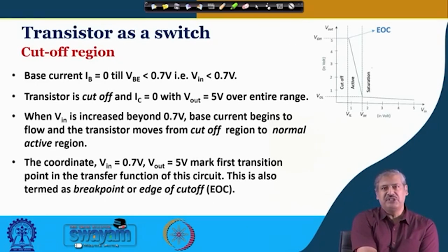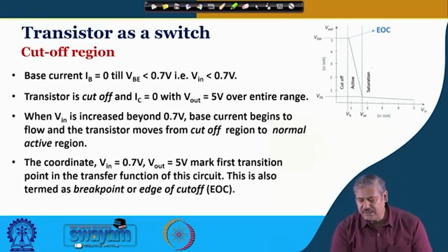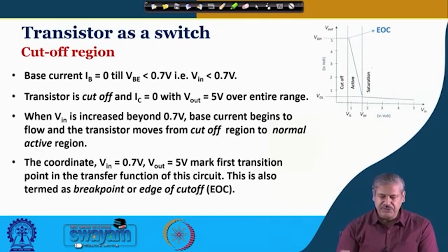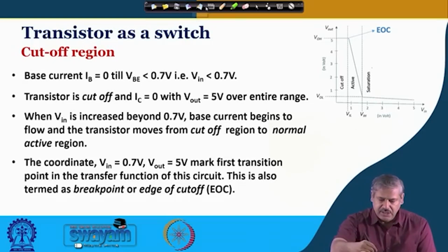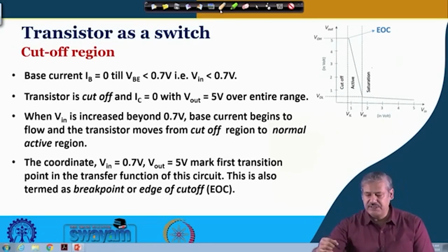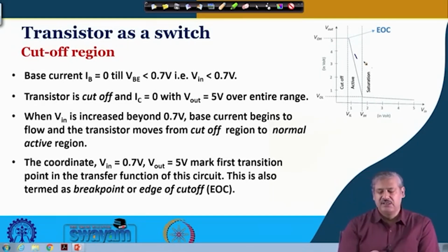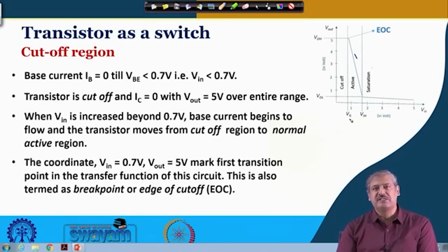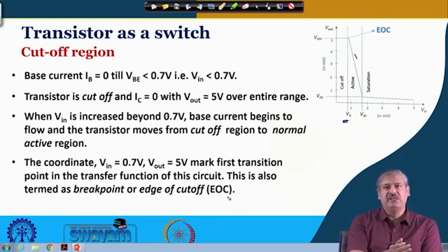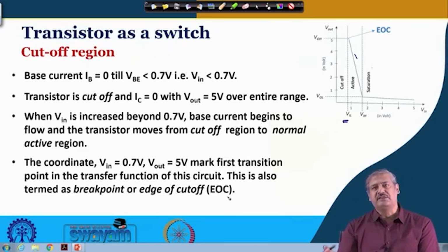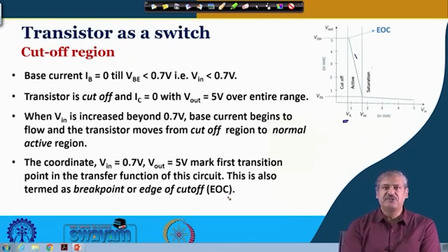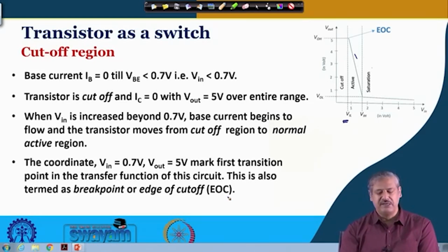With this, let us look at that characteristics. The first thing that we shall try to get is at which voltage this fall starts occurring. In this particular case it is very simple: VIL is nothing but the voltage when it comes out of the cutoff region and enters the active region, and based on the values we have already taken, it occurs at 0.7 volt.